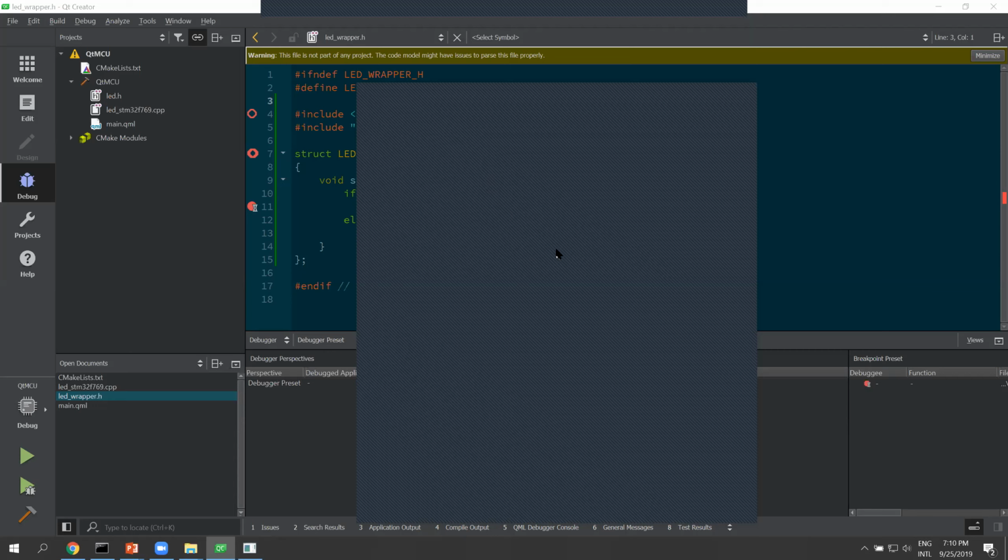Then we have a question about screens, and how to know if it's compatible with Qt. Well, I would say that it's not directly related to Qt. It's more related to the board itself. Of course, you will need some drivers, but basically, when using Qt Ultralight on a given board which we do not support out of the box, meaning also on another screen, there will be some adaptation to do inside Qt Ultralight to make use of this new screen.